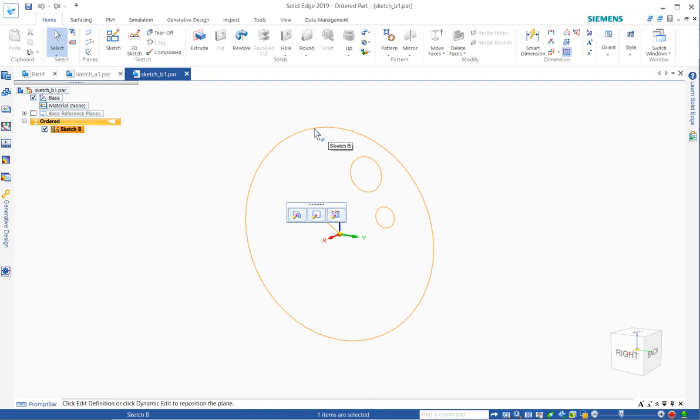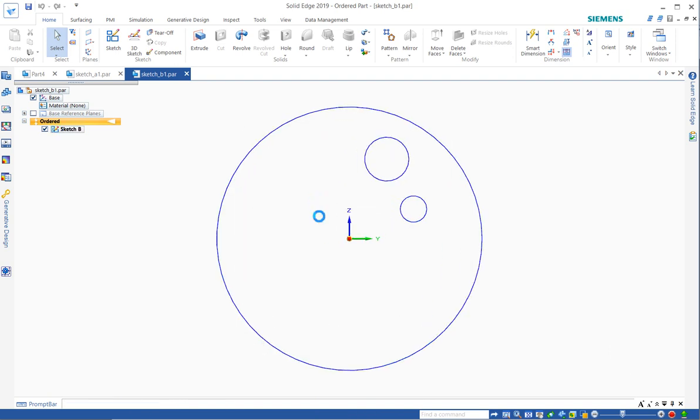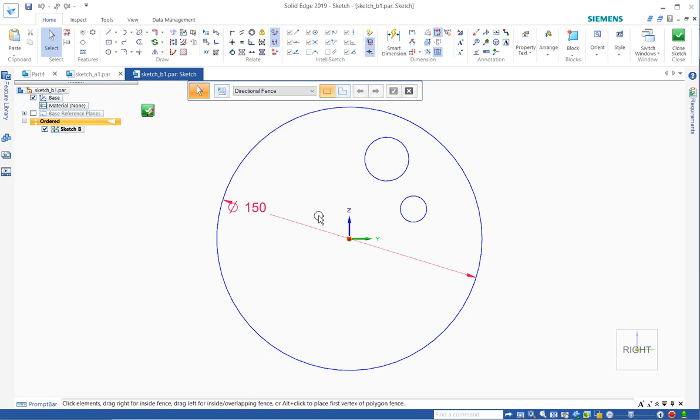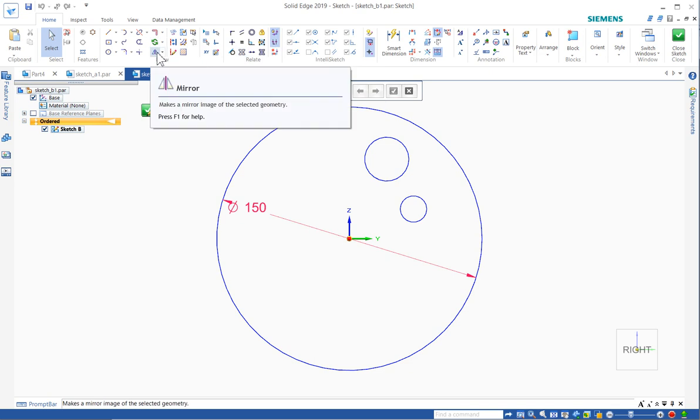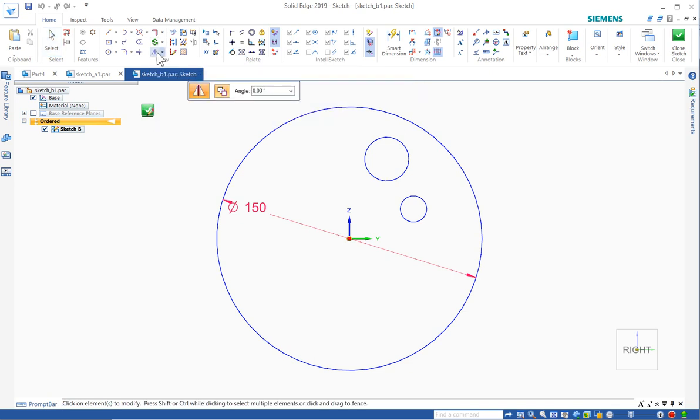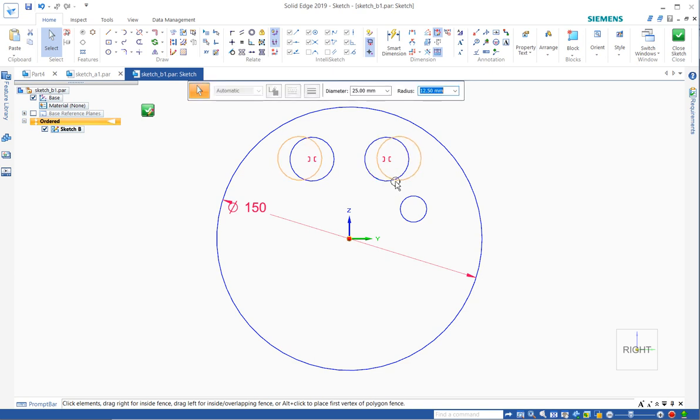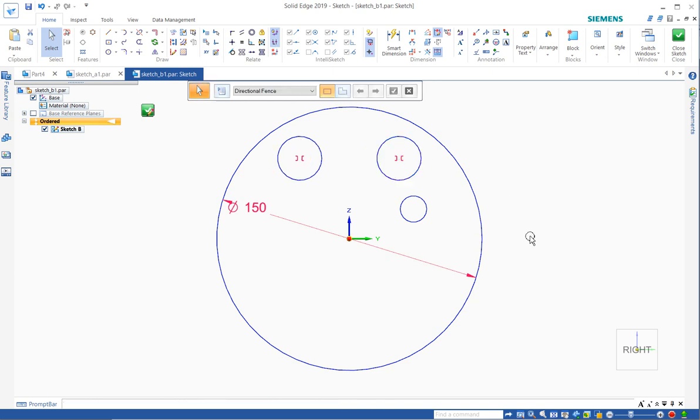This is another sketching activity. They're going to mostly have you learn about creating symmetry. So I'm going to click it and edit profile. Takes me into here. So if I created copies, this command will create geometry or move geometry. So the copy button is pushed in. If I pick this and then I pick an axis, it will actually create a copy of it, but it also puts a little relationship on there.